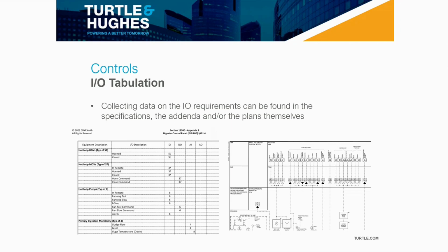I can't tell you how many times over the years someone will say, hey, here's the I/O I need for this project. Can you help me lay something out? And it will say 24 discrete inputs, 12 outputs, 4 analog in and 4 analog out. And I'm like, well, is the analog in 4 to 20 or 0 to 10 volt? Is the discrete inputs, is it AC? Is it DC? What about the outputs? AC, DC, or relay? We need those kinds of details.